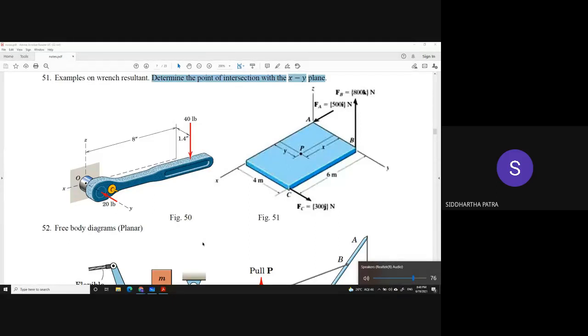For example, you can write in the end, let's call the components of the resultant moment with respect to P, which is MRP, let the components be mx, my, and mz. Then mx by rx should equal my by ry, which should equal mz by rz. Now that is basically two equations. There are two equal signs, which means there are two equations. Those are the two equations which will lead to the solution of the two unknown coordinates of P, x and y.